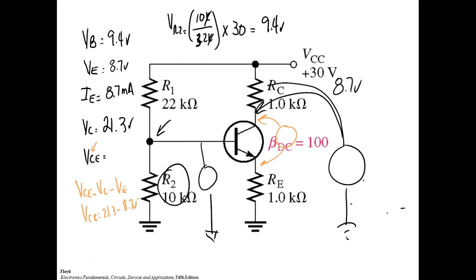And this amplifier here is going to give us a gain of 1, so it's not even worth our time. This is a good circuit just to get an understanding of how to calculate these dBs. This would be a junk amplifier, because if I don't get a gain out of it, it's worth nothing, right? We could get a current gain out of this, depending on the load, but one of the big advantages of a common emitter is we get both a current and a voltage gain out of it.